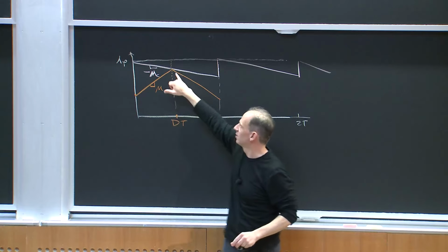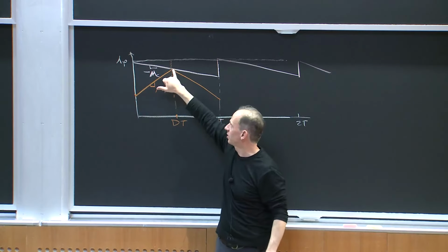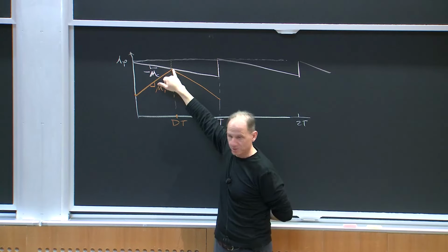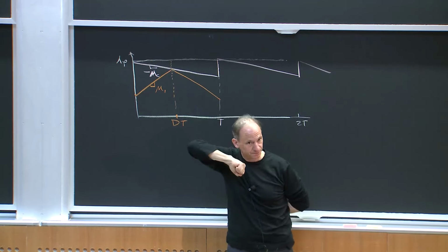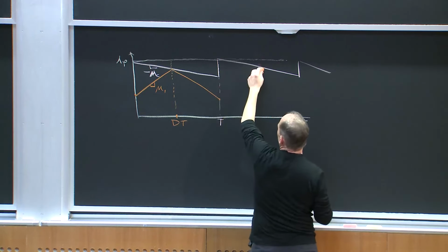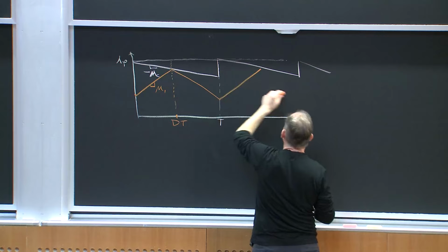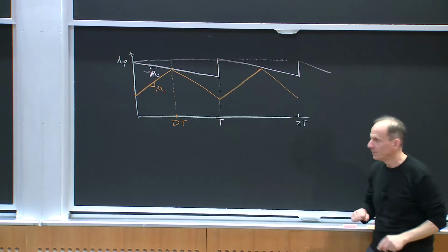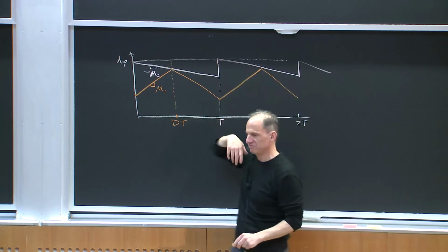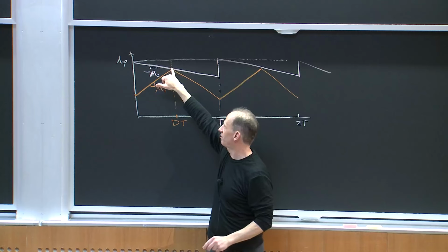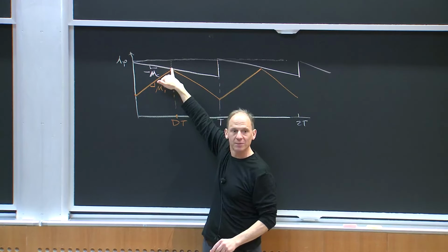So this is, say, dt, right? The switch turns on at the beginning of the cycle, but it turns off. Instead of me setting a duty ratio explicitly, I'm going to implicitly determine the duty ratio based on this peak current. Okay? And then, beginning of the next cycle, I do the same thing, right? I turn the switch on, it rises, it falls, right? And I get the same kind of general behavior. It's just that instead of saying turn the switch off after some time, dt, I'm going to say turn it off implicitly when it hits some current that I command. Any questions about that?